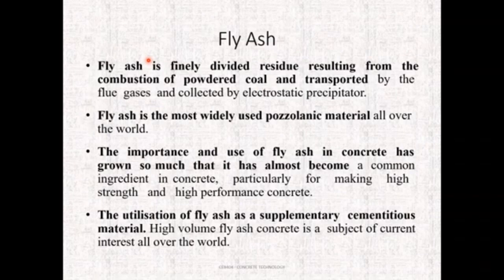Fly ash. Fly ash is a finely divided residue resulting from the combustion of powdered coal, transported by flue gases and collected by an electrostatic precipitator. Fly ash is the most commonly used pozzolana all over the world. The importance and use of fly ash in concrete has grown significantly, particularly for making high strength and high performance concrete. Utilization of fly ash as a supplementary cementitious material is a subject of current interest all over the world.